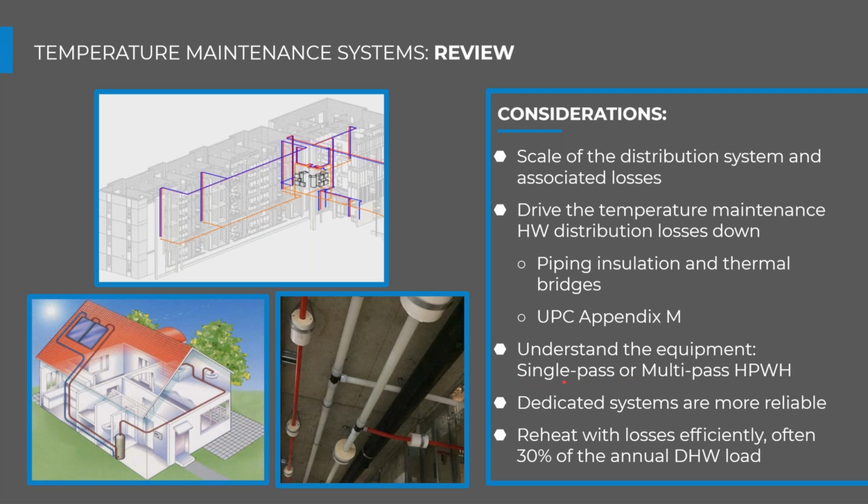If you're single pass primary heat pump or a multi-pass primary heat pump, you're going to approach the commercial heat pump water heating system design a little bit differently. So understand what you're working with there. And then dedicated systems using single pass equipment are typically more reliable and higher efficiency than doing a combined system.